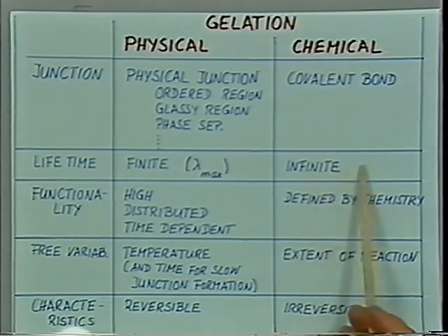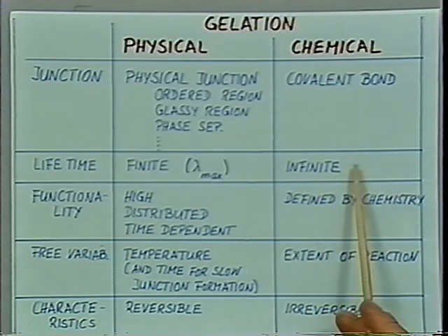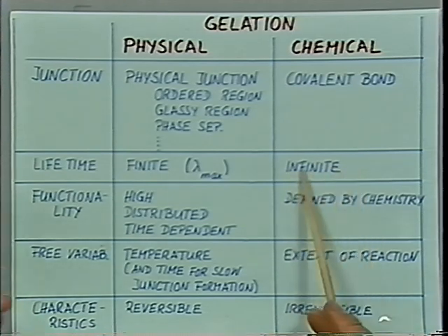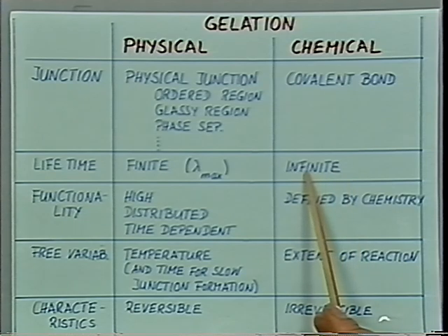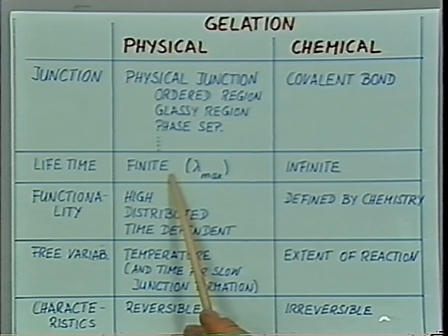In the chemical bonded system, the relaxation time at the gel point was infinite. The lifetime of the bonds is infinite, and certainly the gel behavior, this power law relaxation behavior, will go to infinite relaxation times. Here, for the physical gel, there might be a cutoff at lowest frequencies, or there's a finite time where it's been cut off because of the finite lifetime of those junctions.